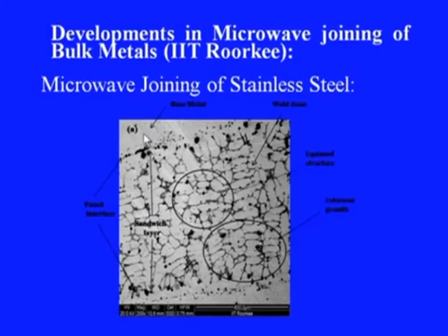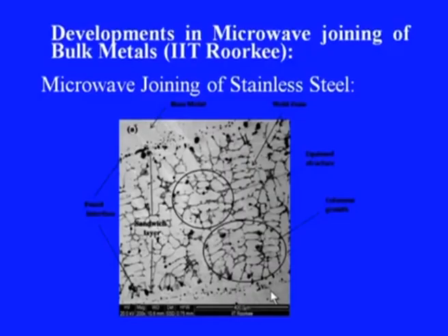Whereas here we can see the relatively different microstructure; these are the base materials or the parent materials which are being joined like this. Upon comparison with TIG welding, we have found these joints to be almost equivalent as far as the strength is concerned. However, in some cases bending strength is found to be less than the TIG joints, but in most of the cases the elongation is more. And the significant thing is that the porosity in this joint is very, very less.